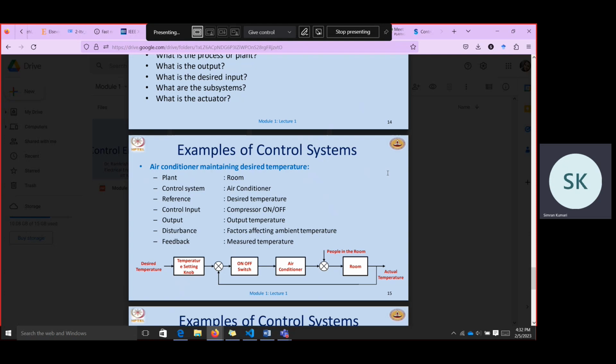Because generally, the controller that we have in the control system is an embedded system kind of thing, or a low voltage system. So it will give a digital output or some 5 volt, low voltage output. And the plant is like a chemical plant, or a microgrid, where a lot of energy is required to be given into the system. There it is not possible to realize that input using that controller. So there comes the actuator, which realizes the input given by the controller.